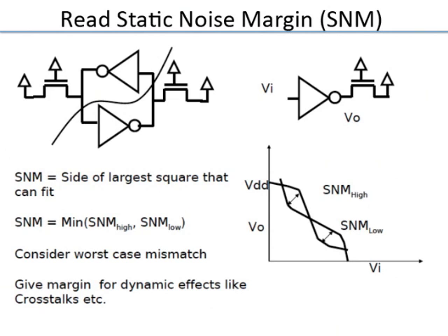So this analysis is usually done when a cell is designed. We have to break it up into half cell and then do a DC transfer curve analysis of the half cell, then calculate this. And then you do this analysis across all different conditions, because especially when you have millions of cells, every cell should work, every SRAM cell. And you remember, transistor to transistor, there will be variations. Across chips, there will be variations. All those variations have to be accounted for.